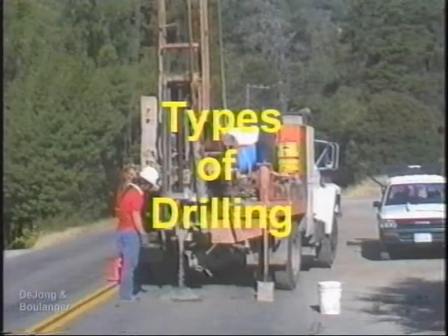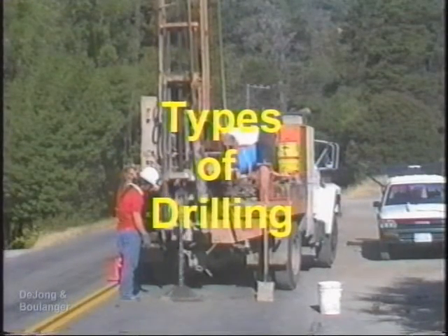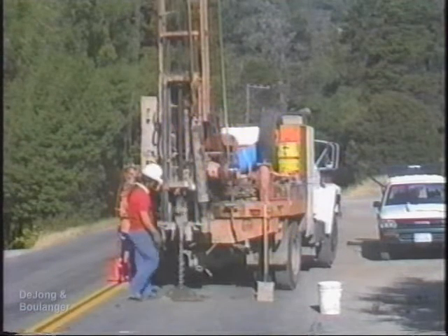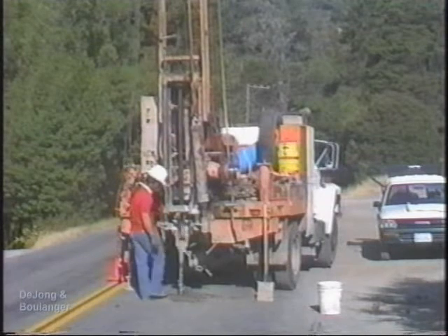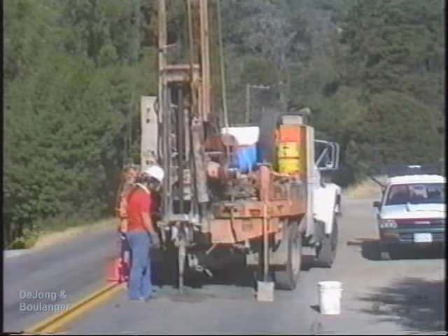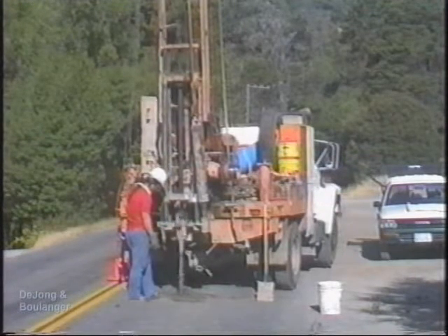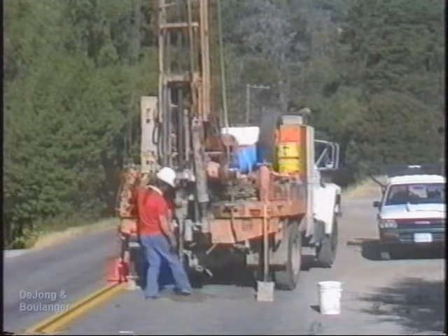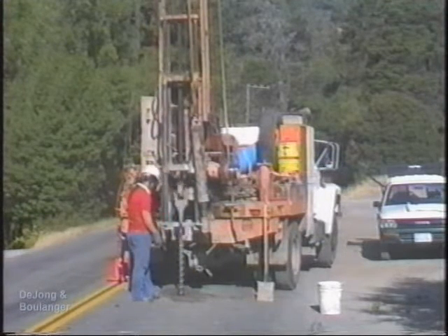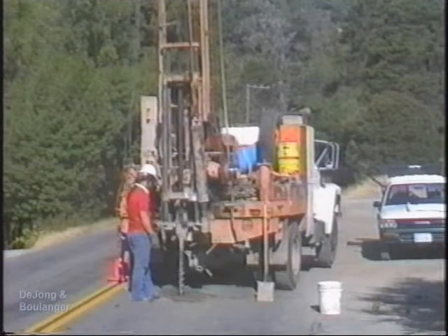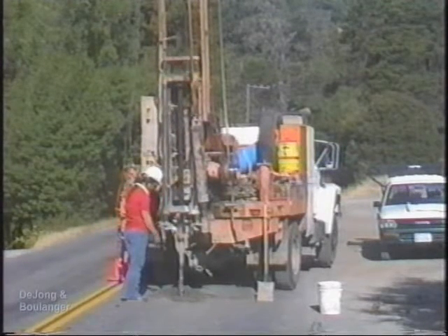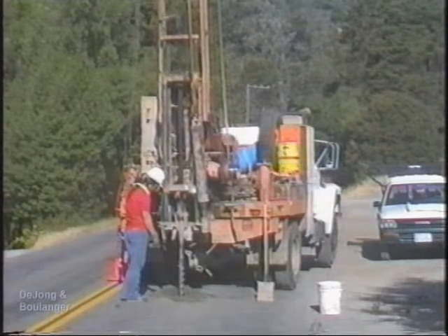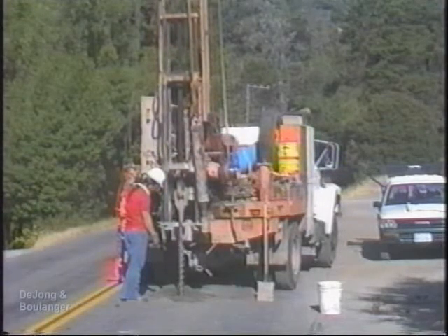Many methods of drilling have been developed, but only four prominent drilling methods will be discussed here. These four methods are solid stem continuous flight auger, hollow stem continuous flight auger, mud rotary, and coring. The main purpose of all drilling methods is to obtain representative samples of the subsurface strata at different depths. These different drilling methods are individually suited to different soil and rock conditions, and thus more than one method may be needed on a given project.